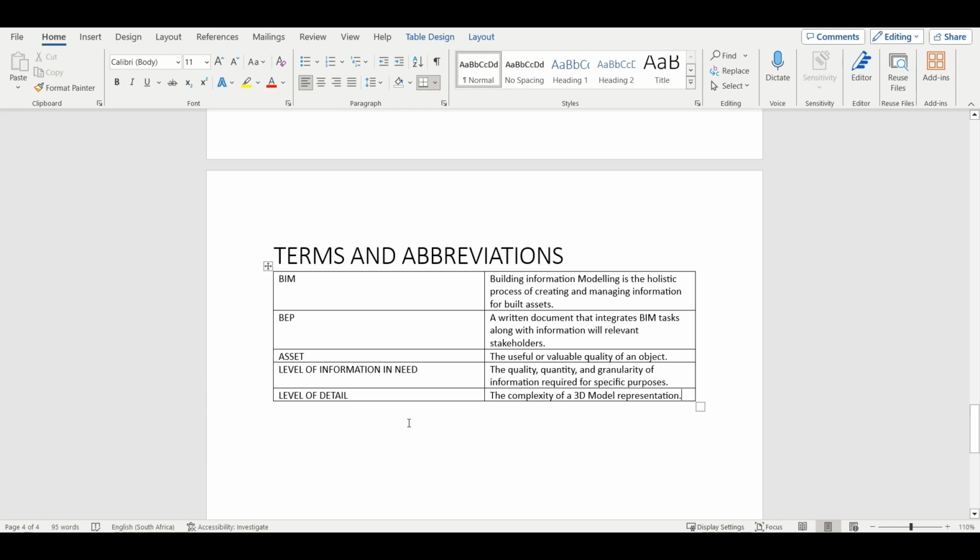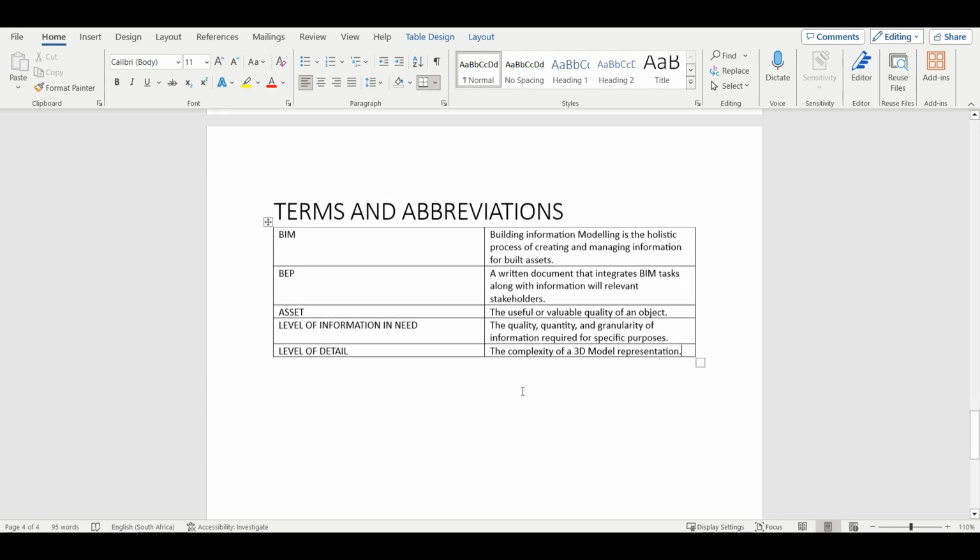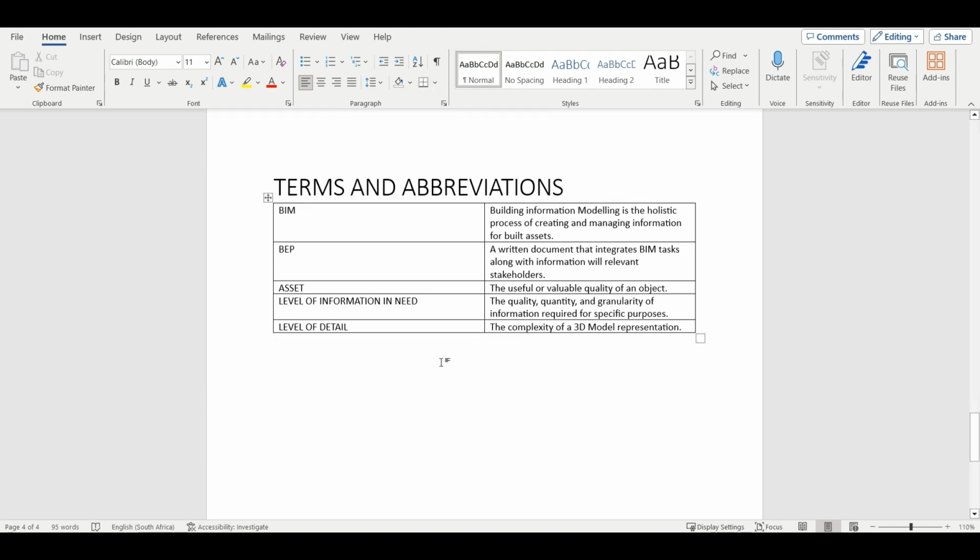But I think there's some modifications when it comes to the BIM standards. So now, instead of level of development, they are using level of information need, which combines the graphical data and also the non-graphical data. So yeah, if you are able to communicate those types of deliverables and also what you can achieve towards the client, then you have a higher chance of getting your pre-BIM execution plan to the next phase.